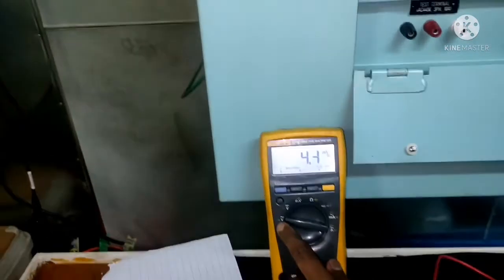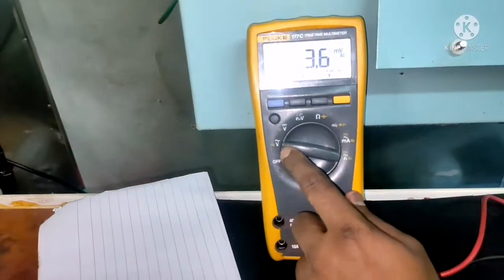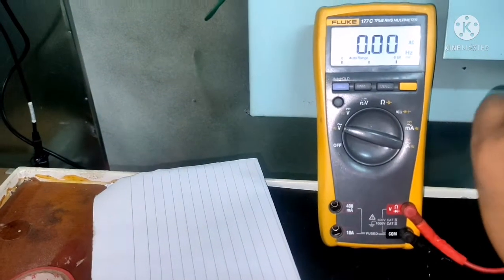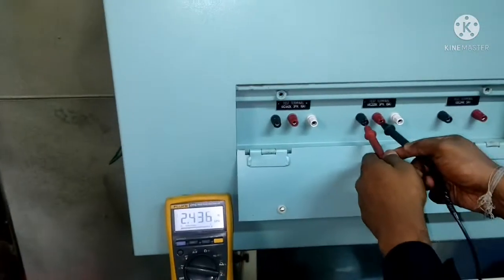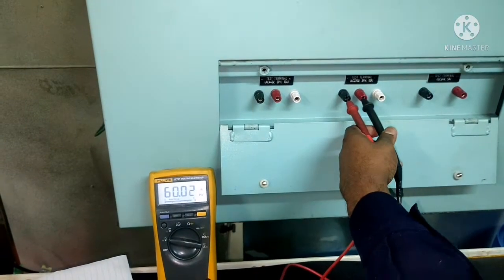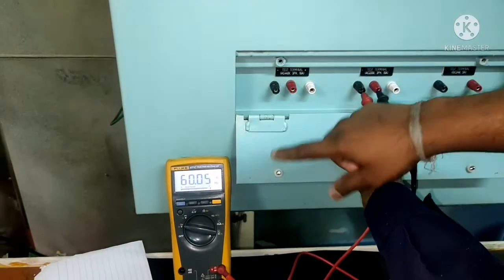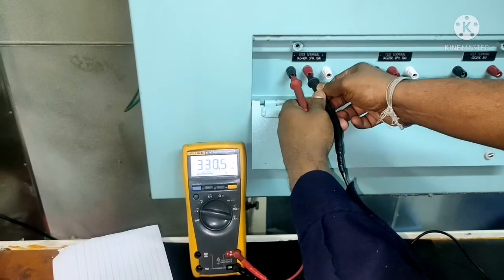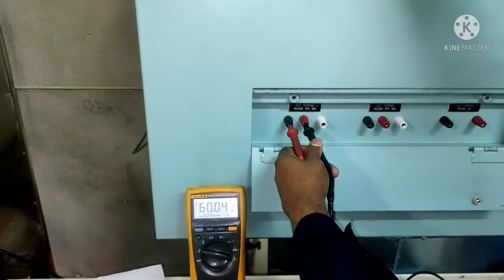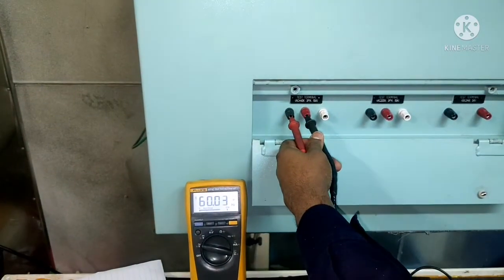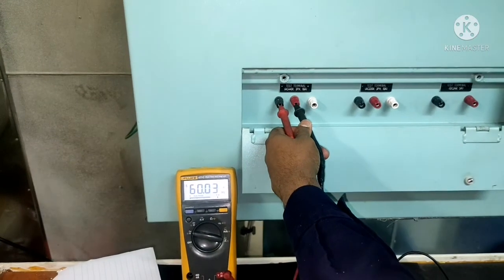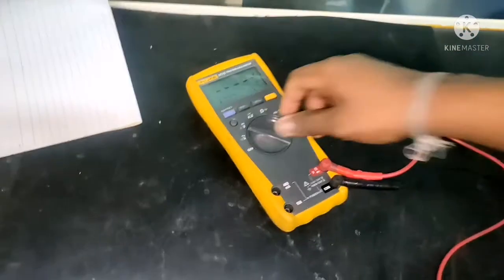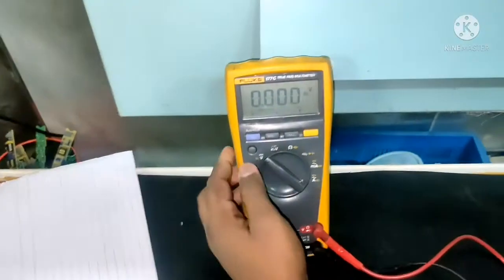As I told you, you can see the yellow color mark over the selector, with which we can find the frequency. All I need to do is press the yellow color button on the top, and you can see hertz, which is the frequency value, displayed on the monitor. Mostly on board ships we will have only 60 hertz, so you are getting the display of 60 hertz. You found 60 hertz for both the AC 440 terminal and the 220 terminal. This is how you can use the selector switch for finding both voltage and hertz.